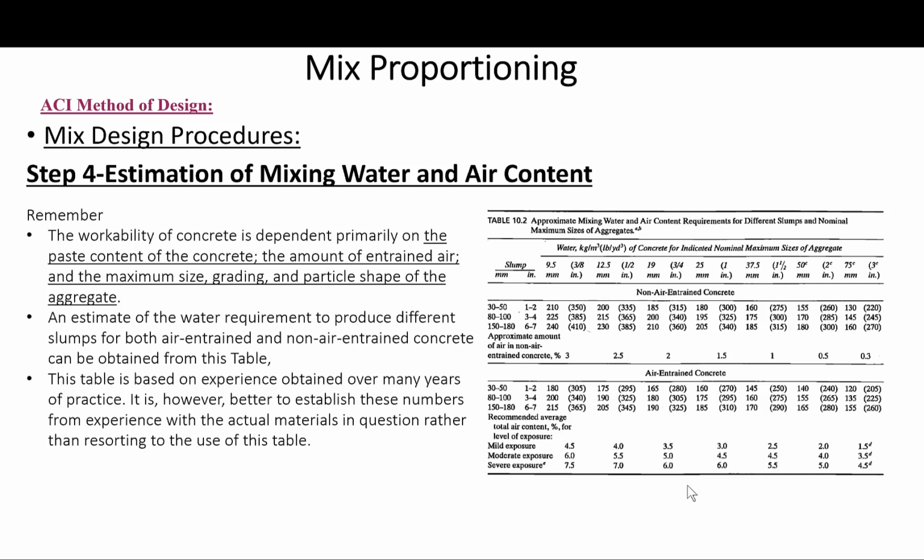This table here shows the approximate amount of entrapped air to be expected in non-air entrained concrete, and gives the recommended levels of air entrainment when required, for different maximum sizes of aggregate and for 3 different levels of severity of exposure. Okay, as you can see here, this is a very comprehensive table.